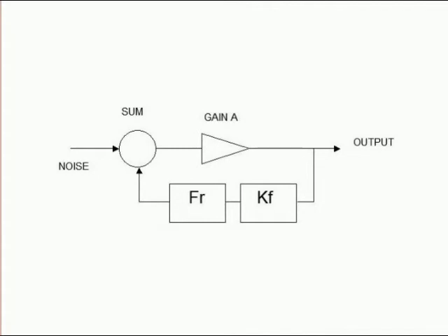A way that this theoretical concept we've set up differs from a practical oscillator is in linearity. A practical oscillator has limiting in it, which is very important to stabilize the amplitude. We all know that in practice you make an oscillator, and even if you don't intend to build any limiting in it purposely, the output is always stable.